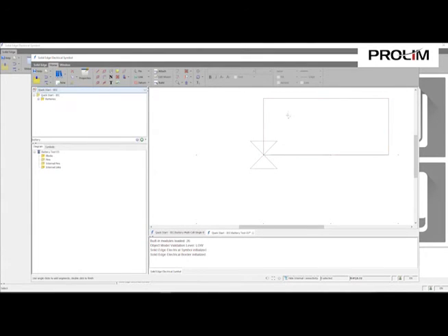So I'm just going to add some simple geometry here. And you can see once I've got the geometry selected, I'm automatically snapping to either the midpoint or the endpoint. Again, it's throwing some intelligence in there for me to utilize as I'm drawing this stuff. And again, I can go up here to L. Each one of these has a shortcut, as you can see here. So if I just type L on my keyboard, I'm back into the line command. I'm just going to create some simple geometry here.